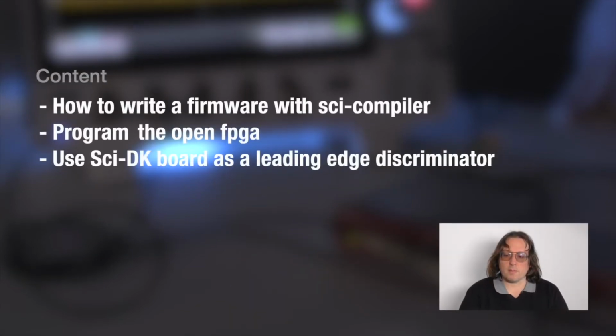Good morning. Welcome to the SCI-Compiler tutorial. In this tutorial we will learn how to create a discriminator using this CDK development kit. In this first tutorial the discriminator will have a fixed threshold, hard-coded in the firmware.